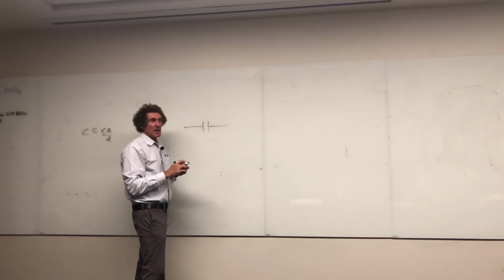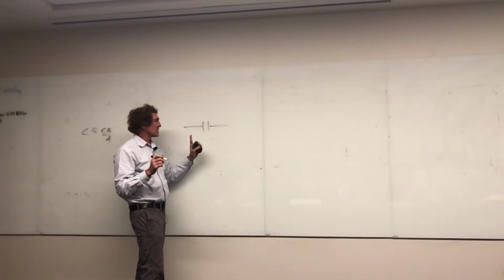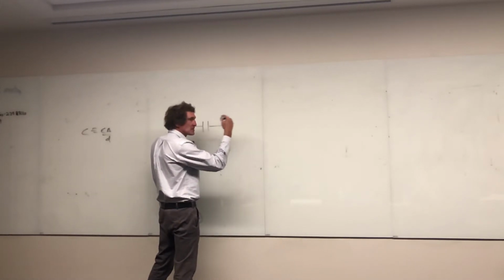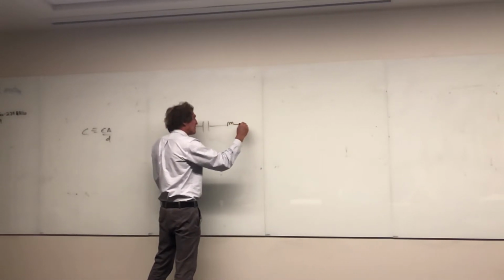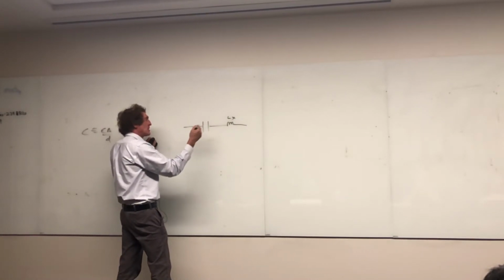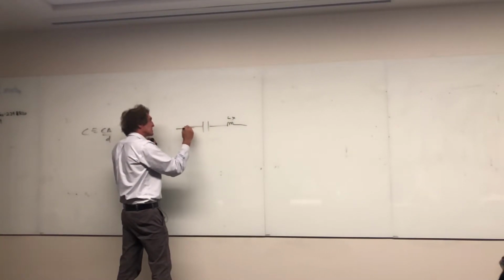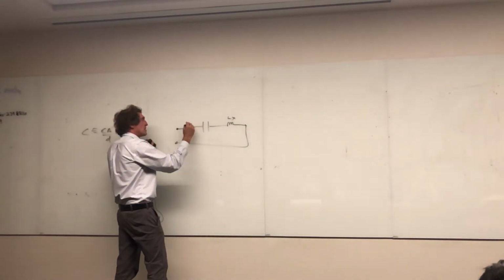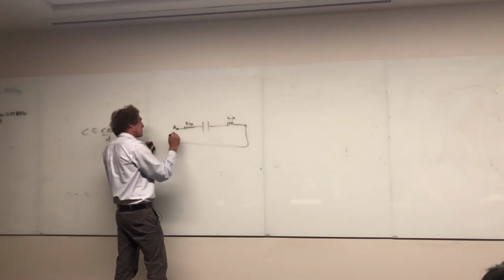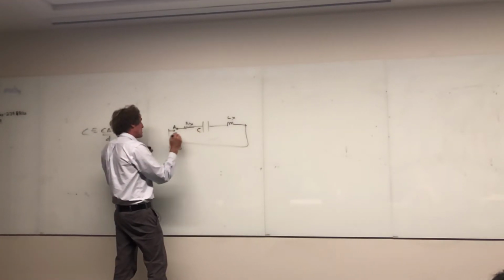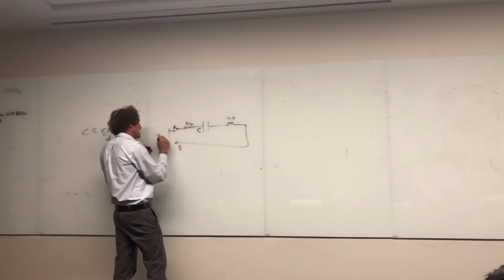So that's the capacitor. The model we're going to use, we're not going to do anything with a resistor in parallel with it or anything. Normally, because there is wire involved, you're always going to have a lead inductance that's unwanted. And whenever you have wire, you're going to have a resistance, R. It's just the nature of the beast. And that's really Rx. So that's what the actual capacitor looks like, the model. And they're easy to get confused.